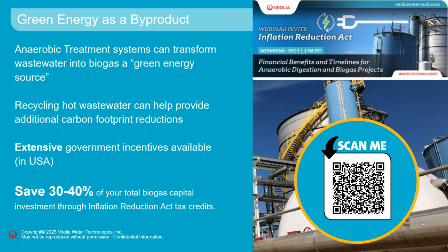There are both economic and societal drivers for mills to consider green energy generation from wastewater. Starchy wastewaters can be transformed into biogas using anaerobic treatment technologies. The biogas generated normally contains 65 to 75% methane, which can be used to displace natural gas fed to a boiler, be converted into green electricity, or be upgraded to renewable natural gas, eagerly sought by utility companies.